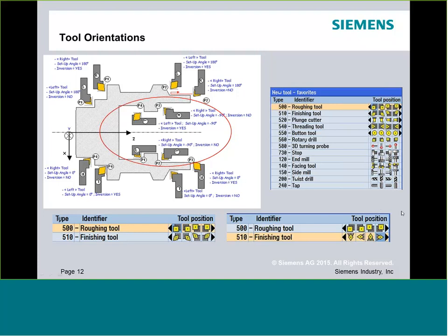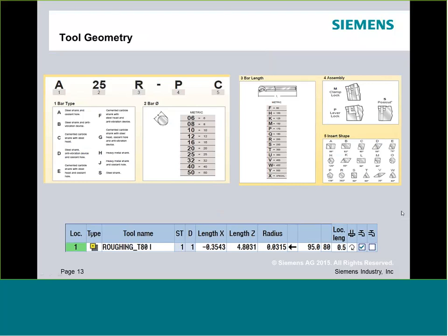That's very typical to what we would see. Now, when you start to look at the IC standard of boring bars, there's a lot of information here. What they're going to give you is the bar diameter, the geometry of the bar, clamping, whatnot. Now, when it comes to that tool holder data, you'll notice down in our lower segment, we don't have any variables that we're tracking anything about the bar. We are tracking the insert geometry. So it's very, very important when you get to ID work that you pay attention to the bar size.